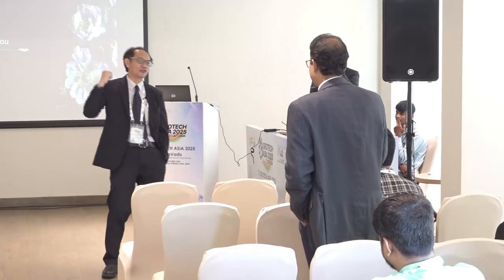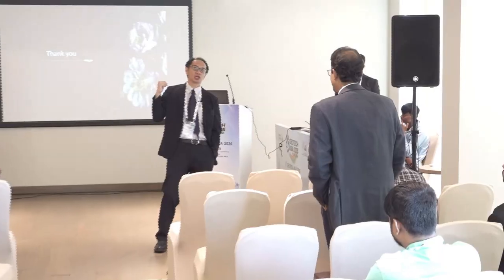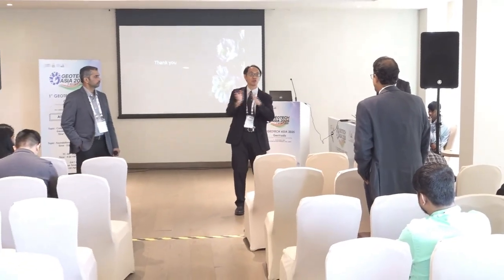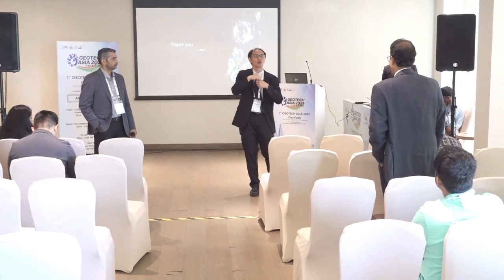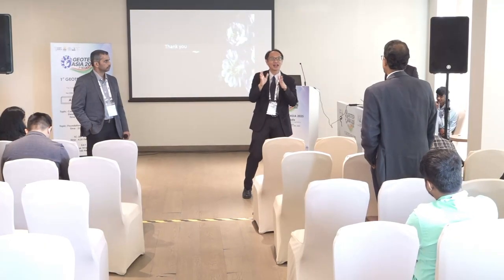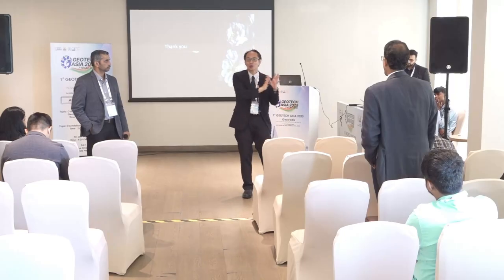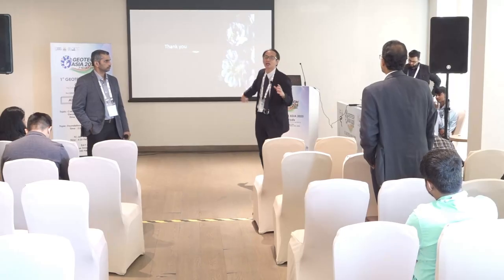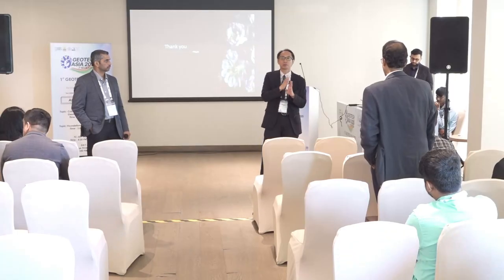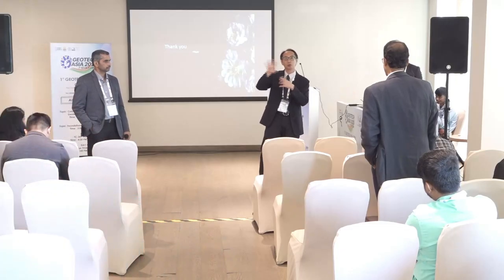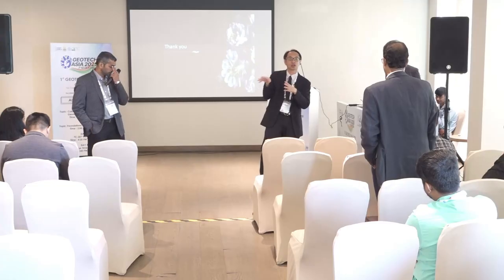Because in fact, in this paper, we actually pay more attention to the wall deformation instead of pore pressure. The issue is we don't have piezometers. What we have is only the observation well. So really, you cannot get what the real pore pressure will be. But by the papers we published in 2023, we think consolidation plays a more critical role rather than creep, based on the portion of the consolidation which we have from the analysis.